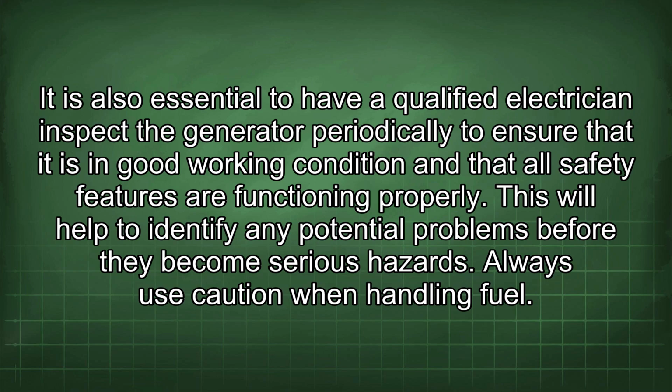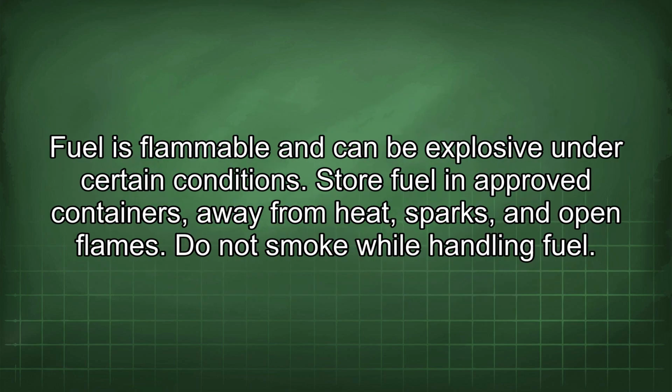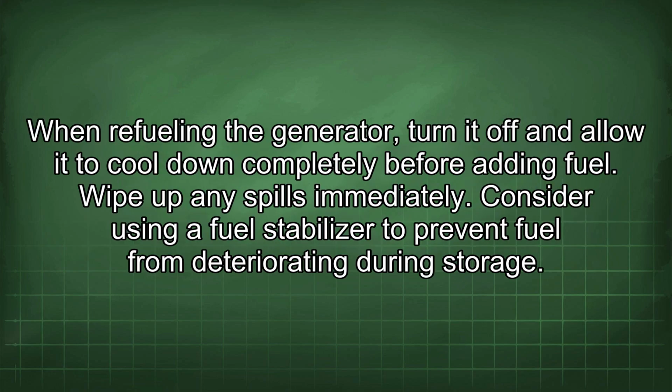Always use caution when handling fuel. Fuel is flammable and can be explosive under certain conditions. Store fuel in approved containers away from heat, sparks, and open flames. Do not smoke while handling fuel. When refueling the generator, turn it off and allow it to cool down completely before adding fuel. Wipe up any spills immediately.